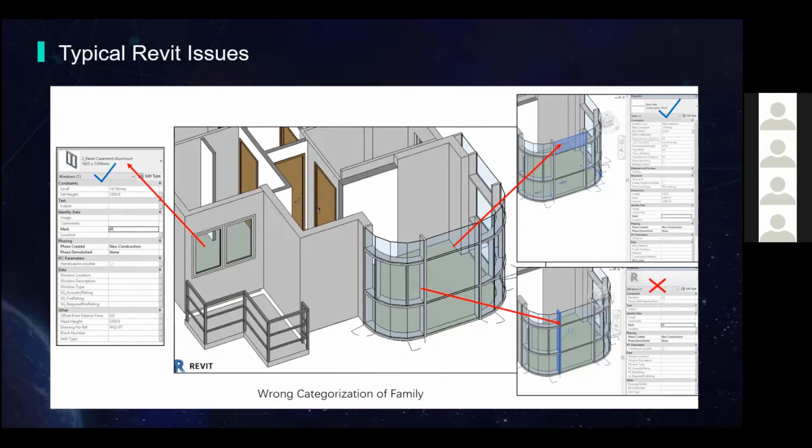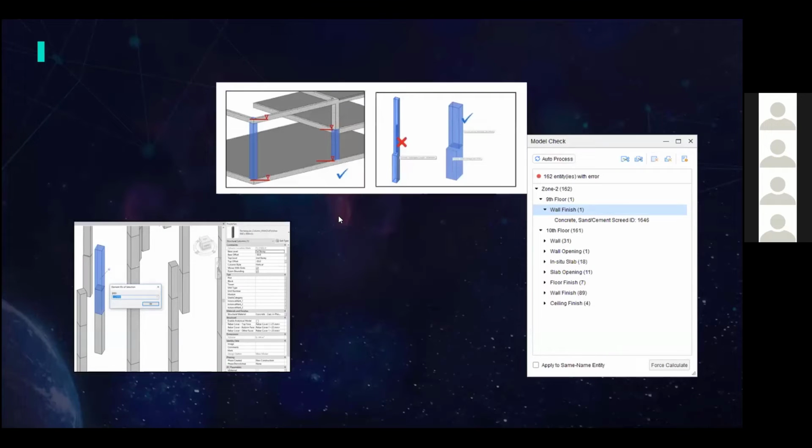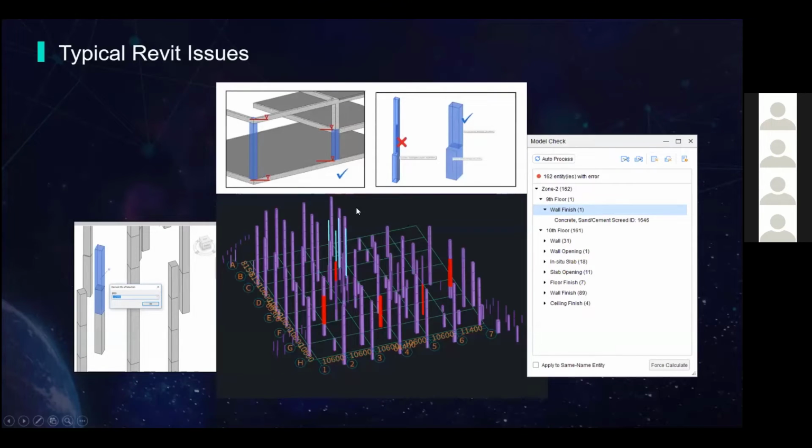Okay, more or less a similar thing here. If you go all the way to the top, it shows inside your Revit model that these columns are going throughout the building, and then you get one quantity on the ground floor and find it hard to separate them out. So in that case, you don't do that.